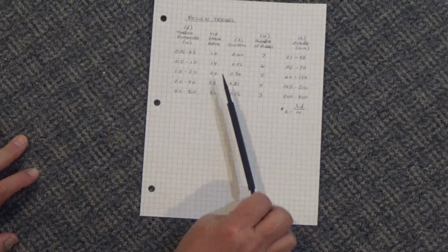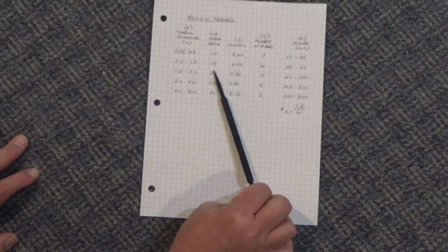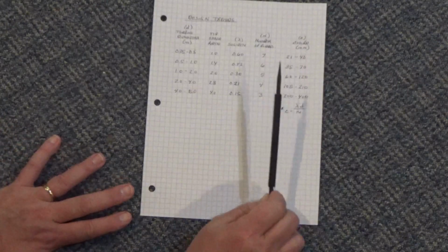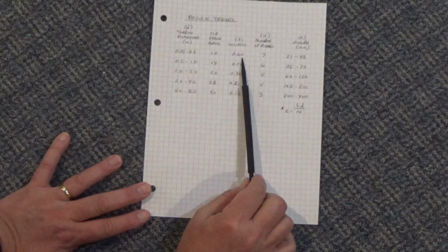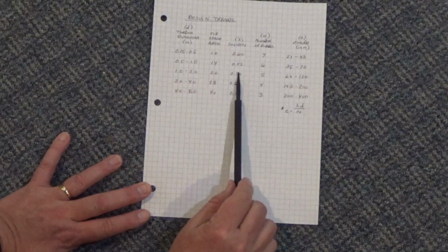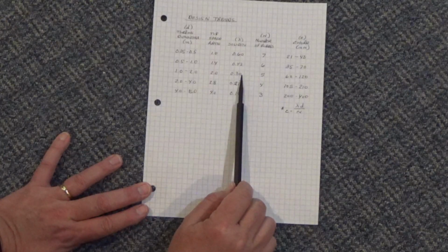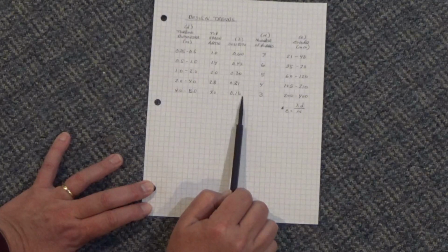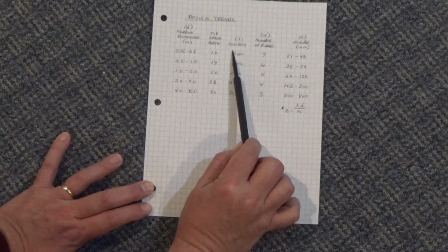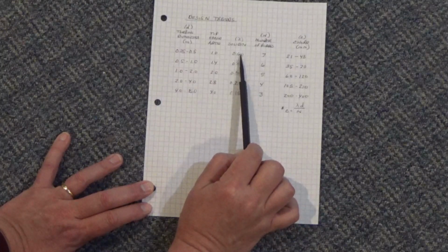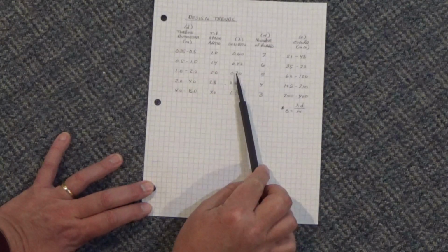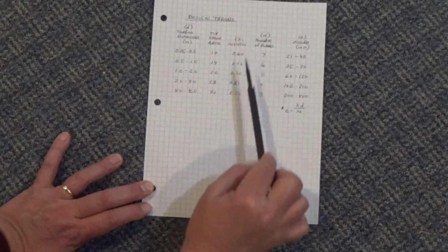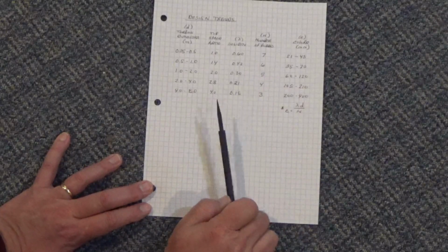And what I did was I just multiplied this by square root of 2, square root of 2, square root of 2. So I just used that multiplier going all the way up. And looking at solidity, I've been finding that 0.3 was pretty good for a turbine. And if it's one of these big ones, they probably run at a lower solidity, like 0.15. And if it's approaching a fixed wing turbine, they usually run around 0.6 solidity. And so I just did the same sort of thing, this times square root of 2 times square root of 2, and so on. I just filled in these numbers to sort of blend.